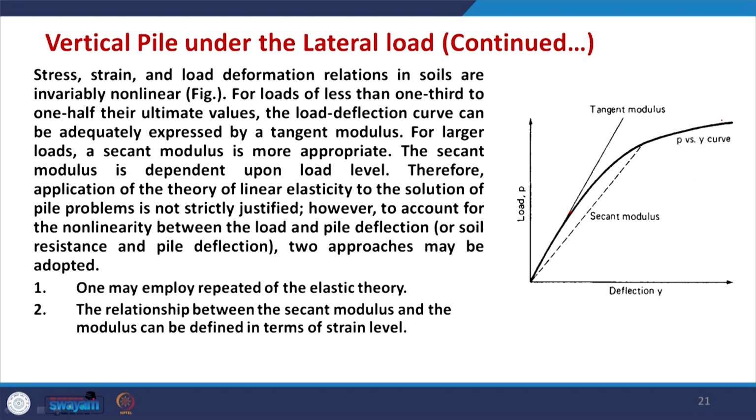So, you need to find the value of modulus at different locations, and the secant modulus is simply obtained by joining this point and this point, and this will keep varying. It is difficult to work with the secant modulus because every time it will keep changing.